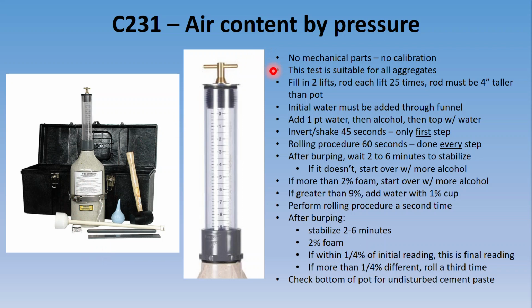And this test is suitable for all aggregates. That will be a question on the written test. Recall last week the pressure test could not be done if you had lightweight or porous aggregates, because the pressure would basically read the air content within those porous aggregates and give you a false high air content reading. So when you have those specific types of aggregates, this is the test that you must use.